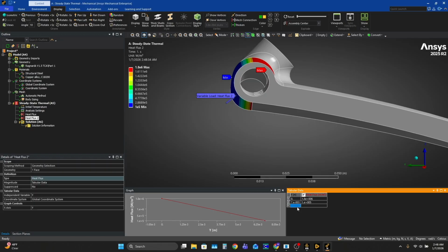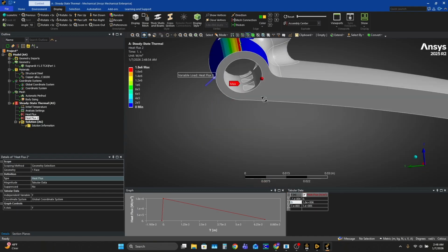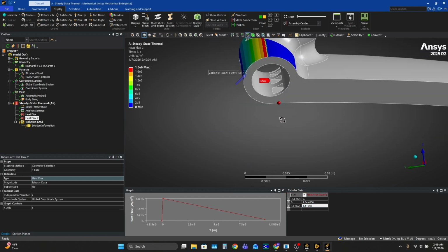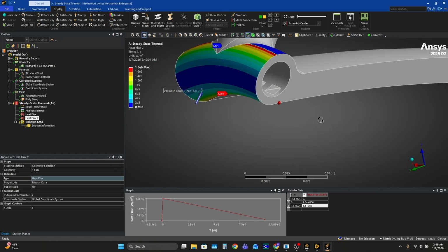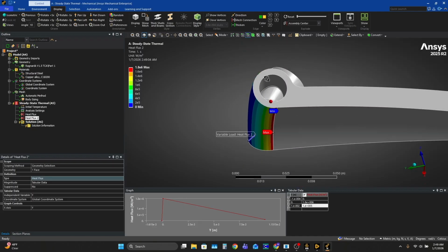So we're going to go negative 0.0001, and we're going to put a heat flux there of 0. So this is kind of what that looks like. It's a little bit uneven, obviously, because we get heat flux on the other side. In fact, this 7 may need to be a little bit larger. It may need to be closer to 10. Yeah, so that looks a little bit better. This is not the best approximation, but in the future, we can hopefully make this better and not have this crazy heat flux over here. But for now, this will do.